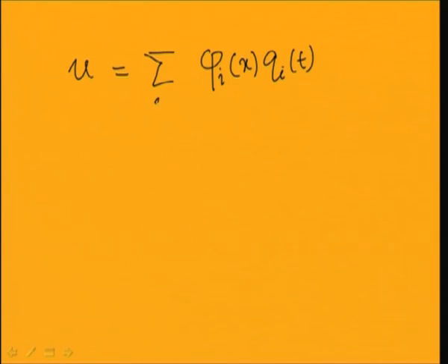So, the free vibration will be a mixture of all these normal modes. Similar to the discrete system, here also this normal mode concept can be applied. Here also we can write the free vibration response of the system, that is u, as the summation of different modes, that is phi i of x into q i of t, where i equal to 1 to infinity.